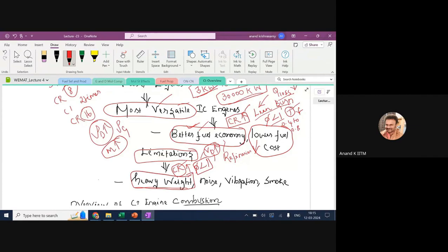So this has disadvantages, mechanical disadvantages. The engine is heavy, right? So the stresses to be withstood are higher in a diesel engine compared to an SI engine since you have heavier components. Okay, and you know the inertia of the components is also dependent on the weight of the component. So all these are high. So you can also say that this will lead to poor vibration characteristics. That is what I have highlighted here as another reason, right? So the NVH characteristics of diesel engines are not on par with SI engines.